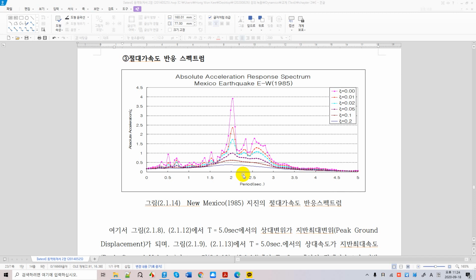You don't even have to memorize the definition of response spectra, but you don't want to forget it, because response spectra is essential information that you put into computer codes like MIDAS, ETABS, or whatever three-dimensional computer analysis is used to design buildings, including low-rise and high-rise buildings. It doesn't really matter. And this is the way you look at the response spectra.